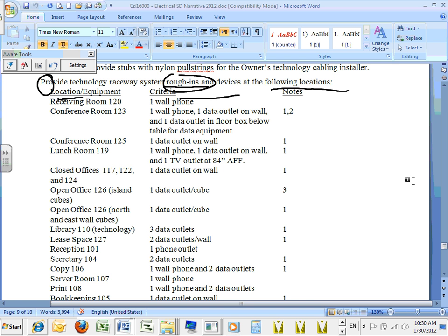So where do you place them? In the floor plan systems. You go there and you place these devices. There are families for these devices, families for the phone, and also families for the data, and a combo phone data. You can place them. All what I'm asking you, Chris, is to just place them. No circuit, nothing.